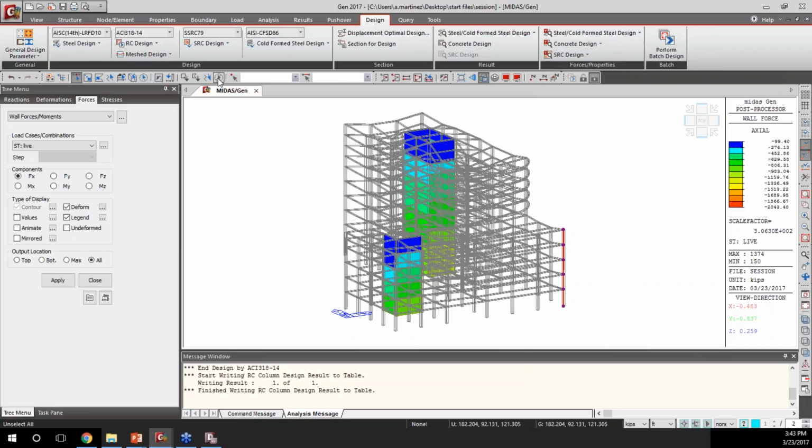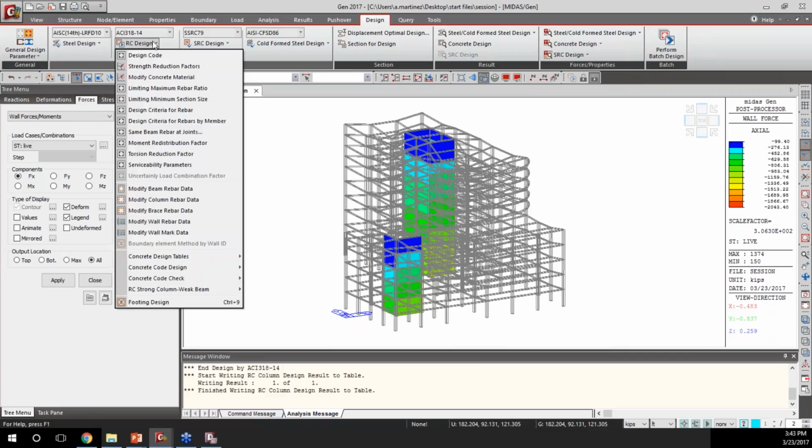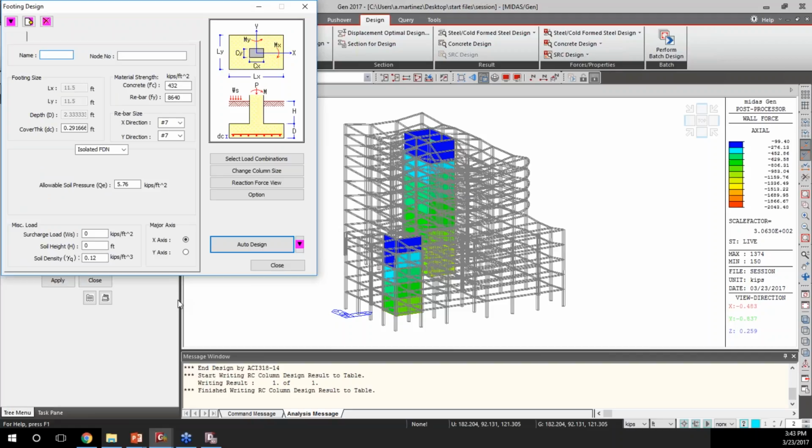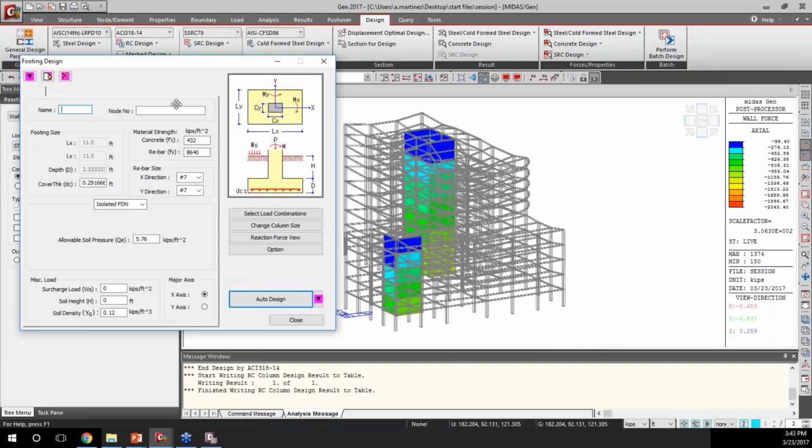Let's now do footing, and I won't do the reinforcement footing. What I'll do actually will be I'll test the code of it, like I'll do a code check, and then I'll connect it to our Design Plus. Design Plus will actually import the loads from this model and the section, the dimensions, but then it will do a design of the section size, not just rebar information. So we just give it a name.